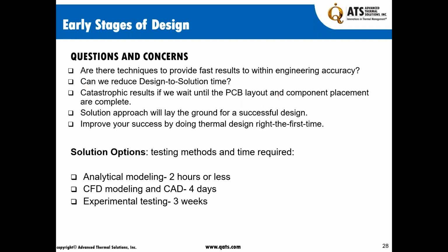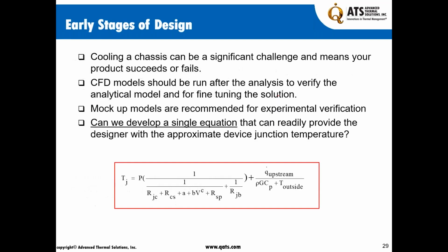People believe data. So if I don't collect data accurately and based on laws of physics, based on a real problem, I don't have a solution. I have a very dangerous solution that I can provide to the field and create a lot of havoc. So in earlier stages of design, cooling a chassis can be significantly challenging, and your product's success could result in success or failure. A CFD model should be run after the analysis to verify the analytical model and fine-tune the solution. Mock-up models are recommended for experimental verification when the